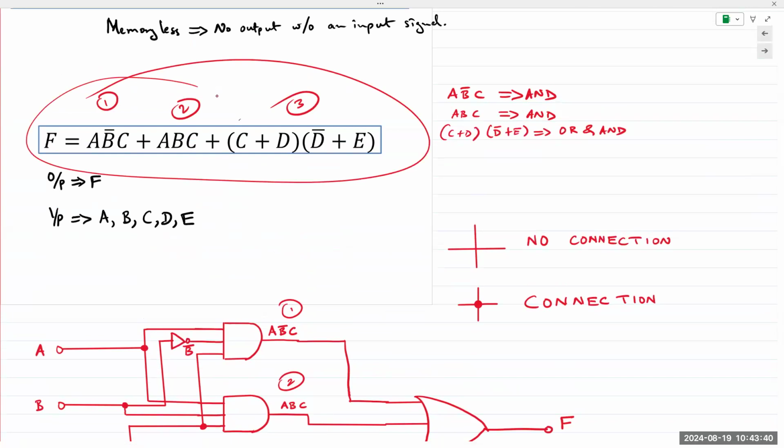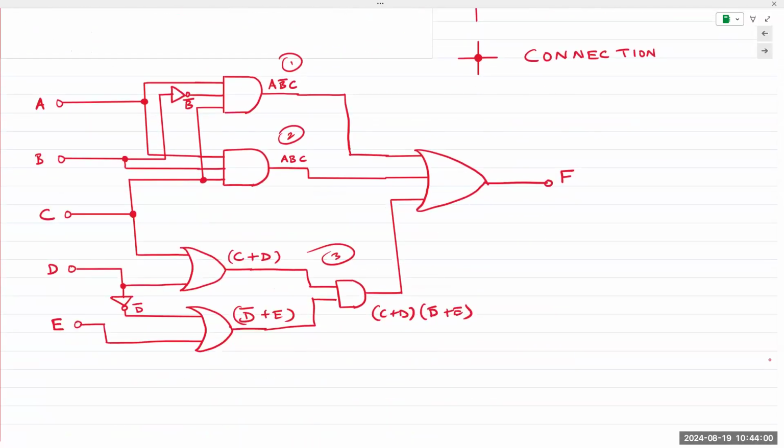Okay. If you have like 1,000,000 gates available to you, then you don't care about efficiency. Right? If you have 1,000,000 gates in that IC chip, 8 or 9 gates doesn't matter. If you implement each one of these, a NOT function and the NAND gate and the AND gates with multiple NAND gates, it's fine. But if your circuit design requires 1,000,000 gates, and all you have is a chip with 1,000,000 gates, you need to ensure that it fits perfectly in there. Otherwise, the chip's not going to work when you try to program it.